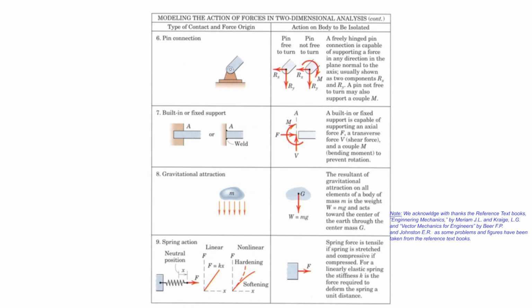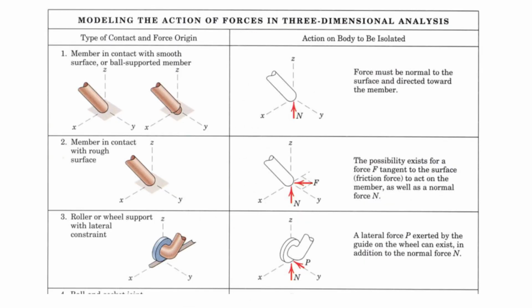As long as you put two forces, that's important. You require a force F. V is upward, we put it. Even if you put it down, it doesn't matter. Even the moment, we put it as clockwise. Even if you put it counterclockwise at this moment, it's okay, as long as you take them into consideration while putting the equilibrium equations. You're not really committing any big mistake by showing the wrong direction at this moment. When you solve it, you'll take the direction into consideration. So it's not a big mistake, even if you show it in the opposite sense.